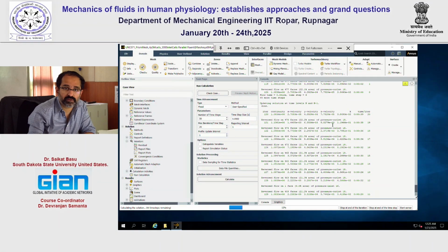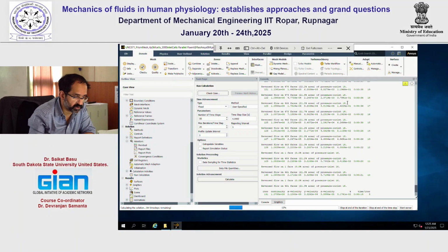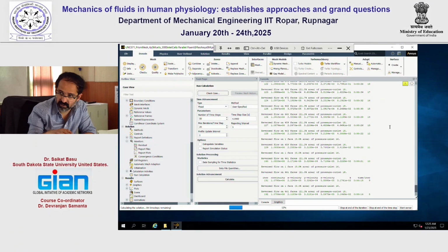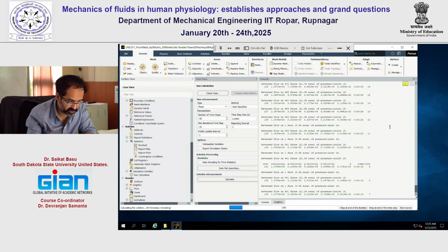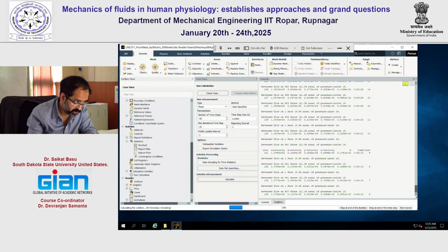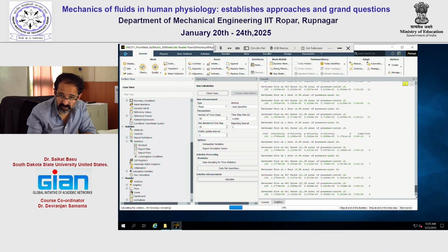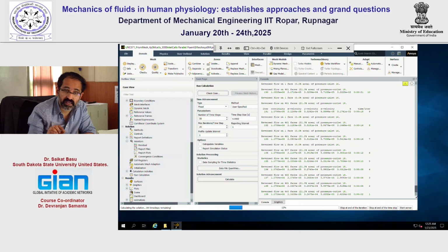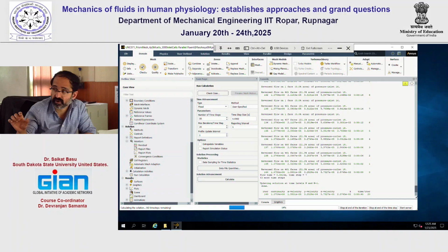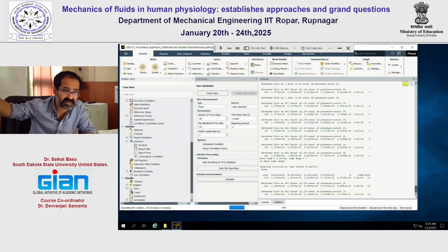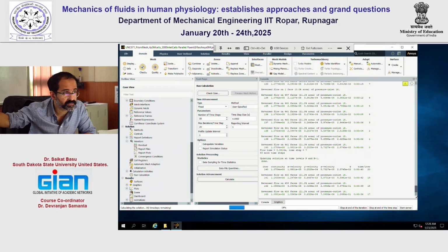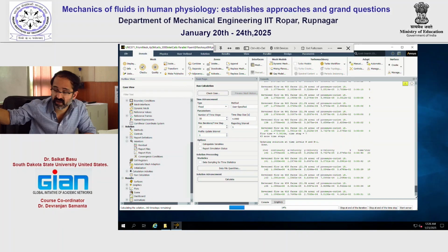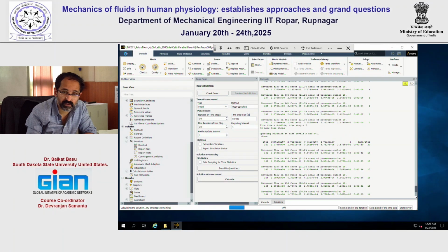But the thing is, you now have a good sense of how the simulation has to be started, right? And you can follow the protocol to do that. So you get the mesh file imported into Fluent and start the simulation. And once the simulation is done, this is important especially for folks who have not used ANSYS Fluent before, go to File and then save case and data files. Case file is the one that includes the mesh information and the numerical setup that we have built up. The data file is the data that is going to be generated. Okay, so you have to save both case and data files, and that is available from this file menu. So file, save case and data.